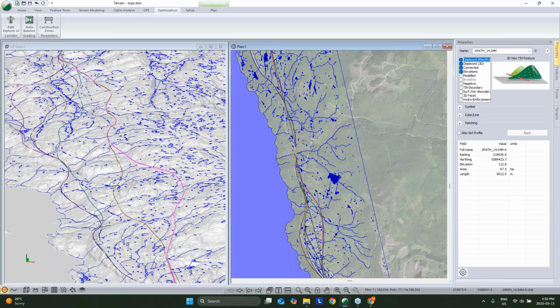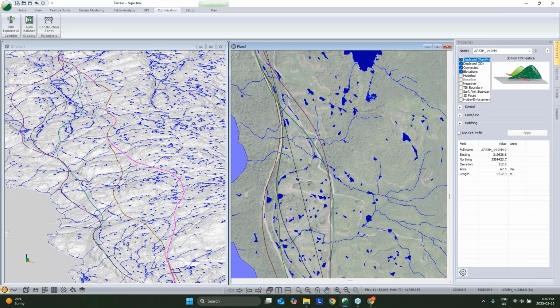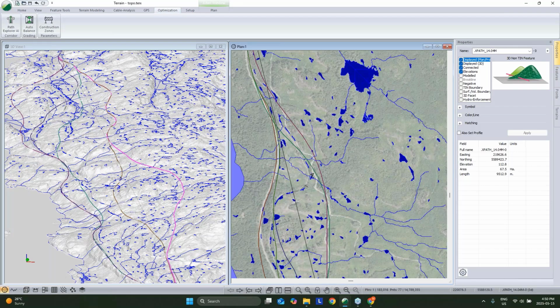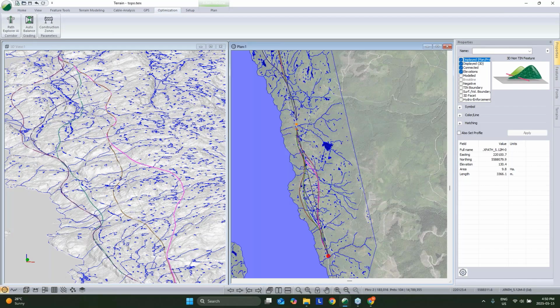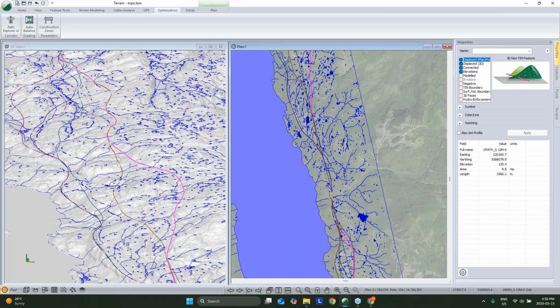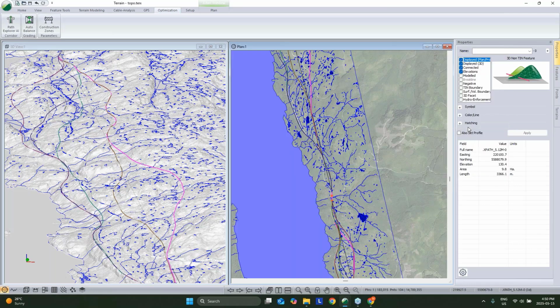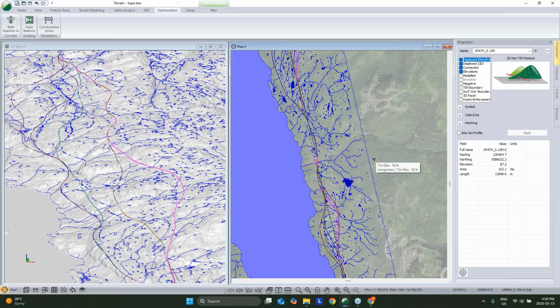And if we wanted to run with that as our solution in location, well, I'd select both of those Path Explorer solutions in terrain. So both are selected right now. I'd right click, modify, join, and I'd take that over into location.